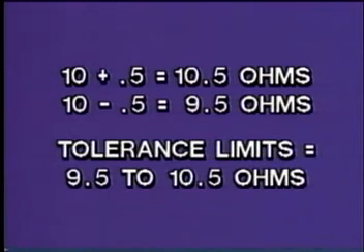Therefore, the resistor is good, because the measured value of 10 ohms falls within the tolerance limits of 9.5 ohms to 10.5 ohms.